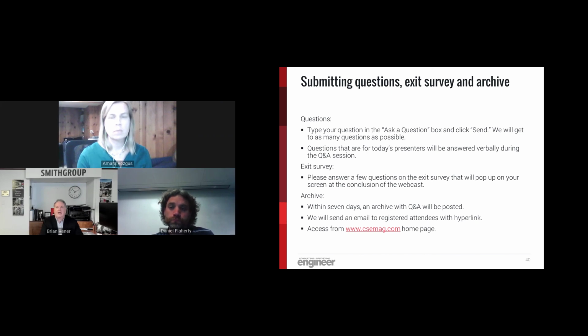I might add, Dan, too, I saw a question about cold climates. I think we have a few Canadian viewers on our webcast today. One of the things we've encountered on the air intakes, Dan mentioned there's two types of air. You have air for heating and you have air for combustion. In extremely cold climates, you might want to stage the air intake into a room or recirculate the air from the discharge, as Dan mentioned, so that you don't fully open your air intakes and bring in minus 10-degree air into the room immediately. So that's another louver control sequence you might want to look at.